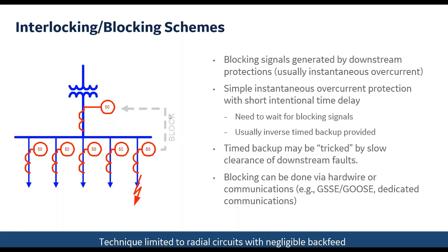So for example, there's a ground, water fell into the panel, and this happens all the time. I used to work for the utility in New York City. So we would have all sorts of grounding issues during snowstorms. And not during the snowstorm, but when the snow starts to melt, the water gets into the cable. There might be some break in the insulation, some degradation in the insulation, and then you would have a fault, you will have an issue.